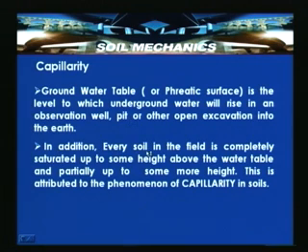In addition, every soil in the field is completely saturated up to some height above the water table. That is what we are discussing. So, what are the reasons behind this particular behavior that we are going to discuss in this class? This particular behavior of soils remaining saturated even above the water table is attributed to a phenomenon called capillarity of soils.